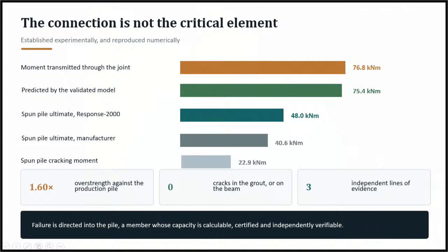And also, even for that load, the grouting or the connection is in contact. So we can optimize the design further in order to make sure the pile is not going to fail, but we can make whatever the critical elements fail before that.